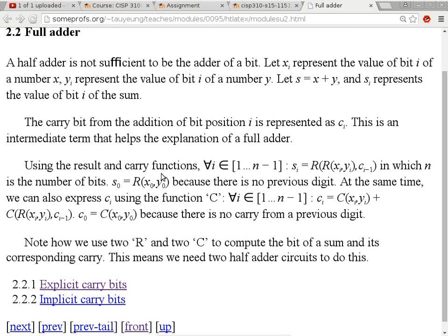I'm not going to ask you any questions about that because this class is not about how to design logic gates using transistors, but just understanding you can use 4 transistors to implement a NAND 2 gate. To me, that is interesting. But the most important part of this discussion is this is a NAND gate, but from the time this signal changes to the time this becomes the actual result of the input, there's a propagational delay. We call it a propagational delay because the transistors take time to charge or discharge and change state.